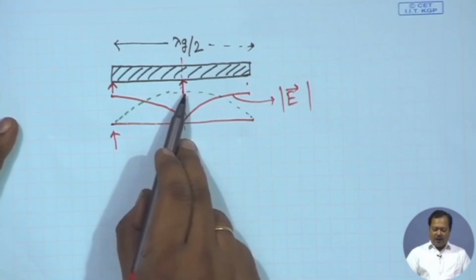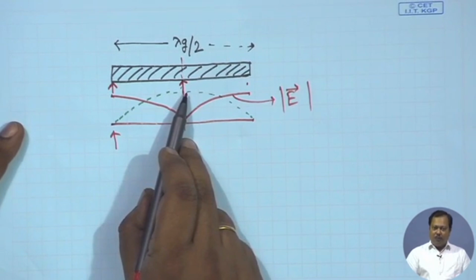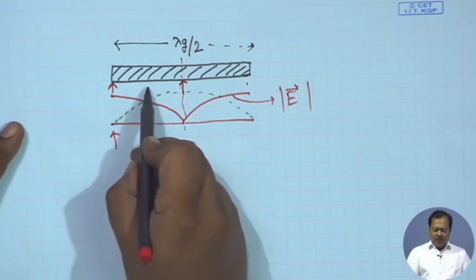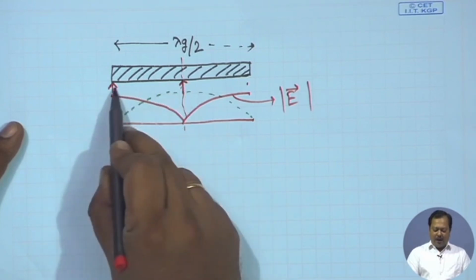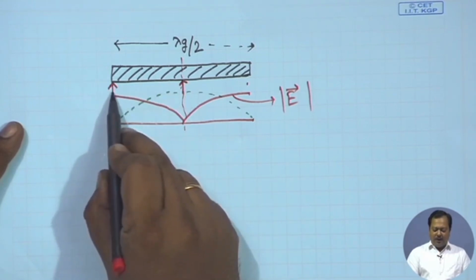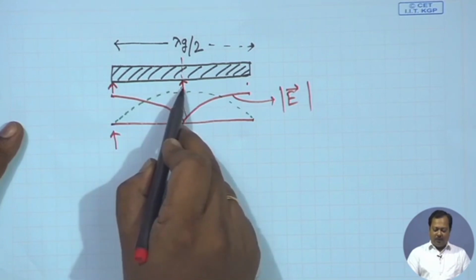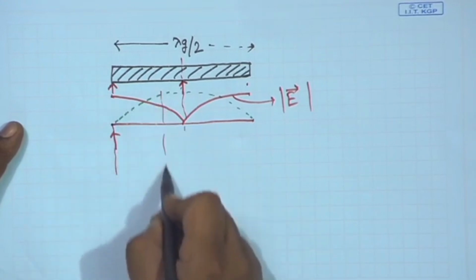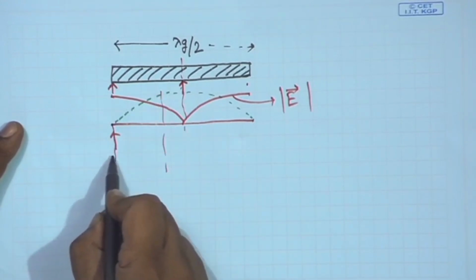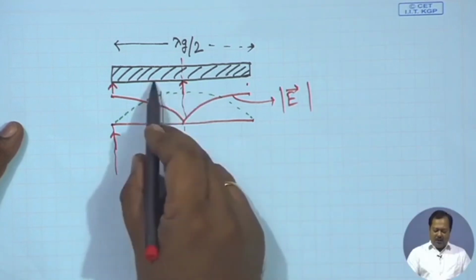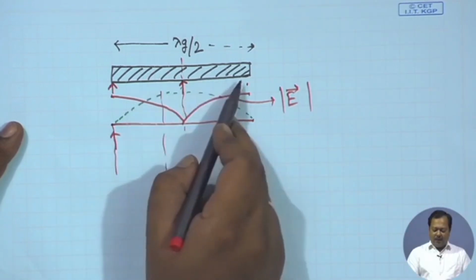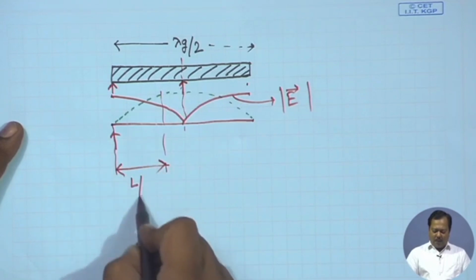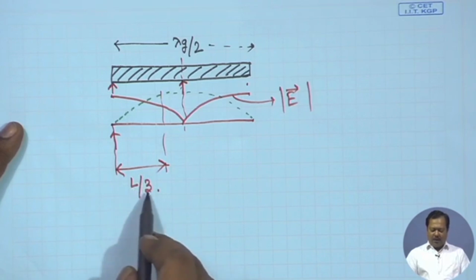For microwave circuits, mostly we use a 50 ohm system. So, for impedance matching, the feed point will be somewhere between this z equal to infinity plane and the z equal to 0 plane, and the thumb rule is that you consider 1/3 length from the left hand side. So, if the length of this resonator is L, then the approximate feed position from the left hand side is L by 3.